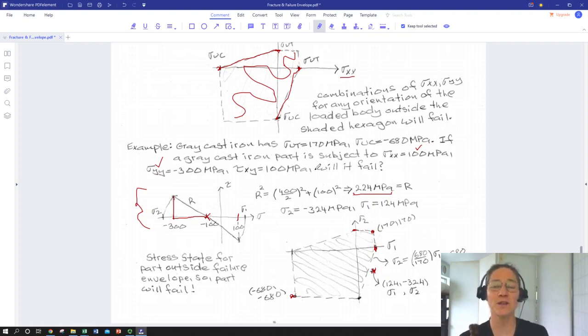And it's also a really, really good warning to us that when we step outside of single axis applied stresses, we can't go apply those values back to handbook values. So for instance, if we just had 124 megapascals sigma 1 and sigma 2 was like 0, then we'd be here and we'd be good to go. It's interesting that the combination of the shear and the compression drove us outside of our allowable envelope.